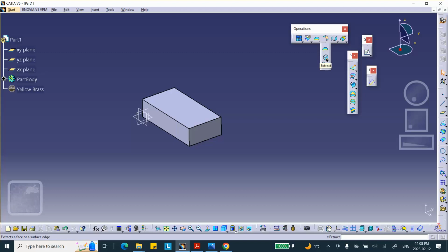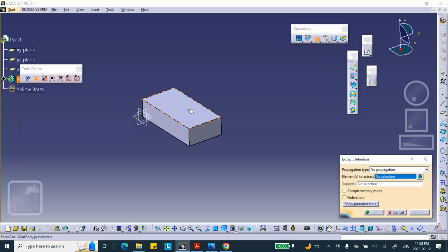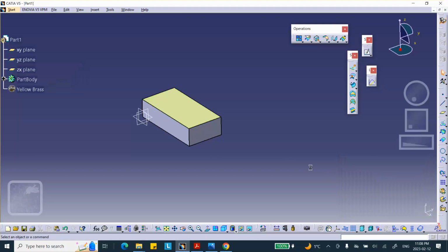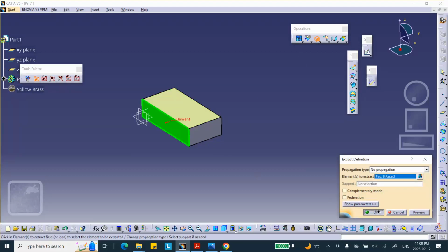Now, when I say extract, if I do this, the window closes. See that? I can't do multiple extraction that way. So if you want to do multiple extraction, you can pre-select both of them and then say OK. Or you do it twice, basically. So where's the extract? This, and say OK.